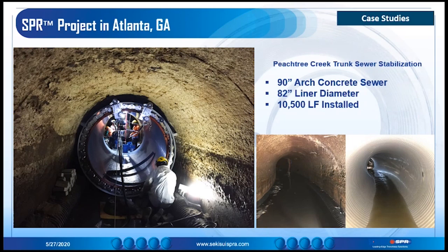During the design process, a fully structural 82-inch round liner was selected to rehab this pipe. As the liner met the fully deteriorated design standard under ASTM F1741-18, a cellular grout was used to fill the annular space. Due to the amount of existing flow within the pipeline, a combination of internal bypassing and flow management at the pumping station allowed the lining to continue during normal flow days.